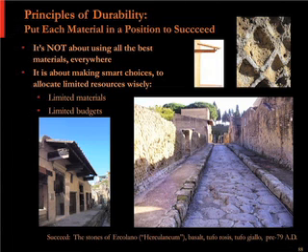So sheltering the most vulnerable areas and shedding the water frequently, at least at every floor, and often more often when windows are involved. And then choosing materials. So it's really not about using all the best materials everywhere all the time.